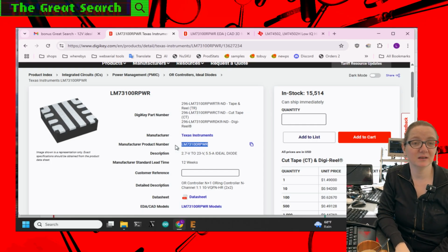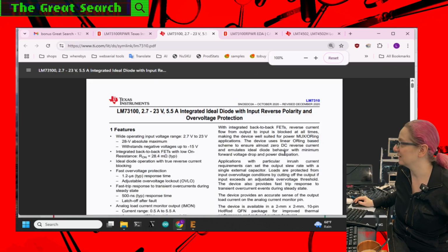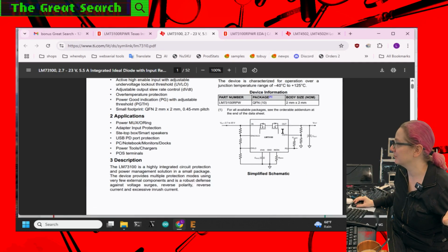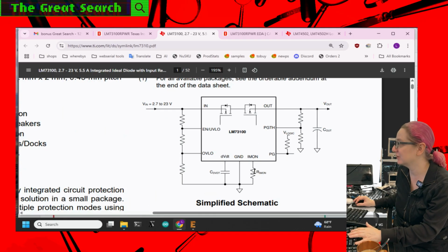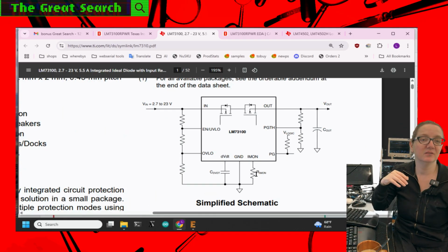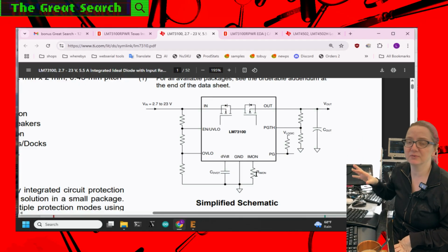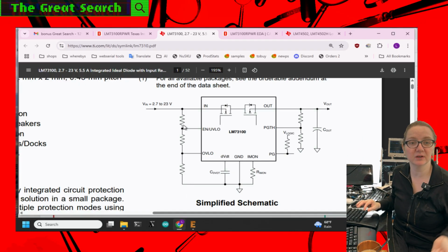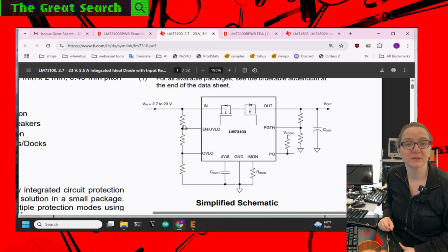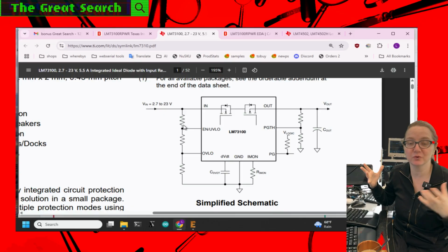And maybe I'll even make one that's a good twofer. One thing that's funky is there's a lot of extra components that you don't need to have, but you can add, because they're like, well, it costs us nothing to add like lockout voltages and stuff. So I don't necessarily need these, but you can configure them. And then of course the enable pin, which is kind of nice, is basically an on-off switch. So you can very quickly turn on and off the diode. So it's not only a diode, but it's also like a switchable diode.